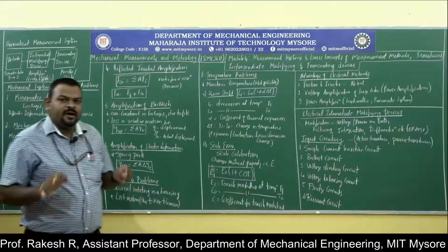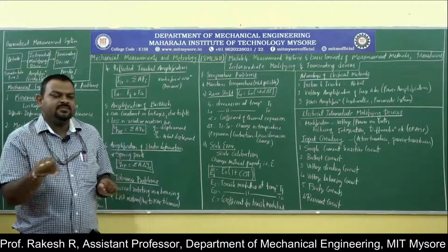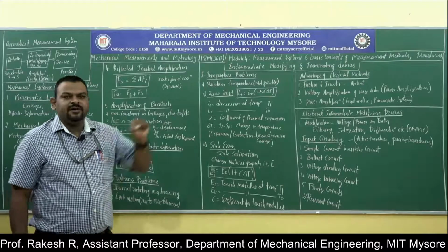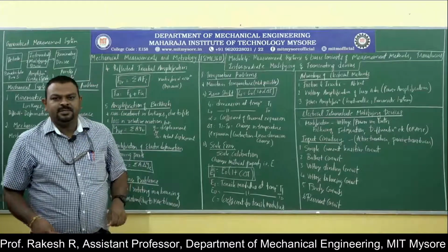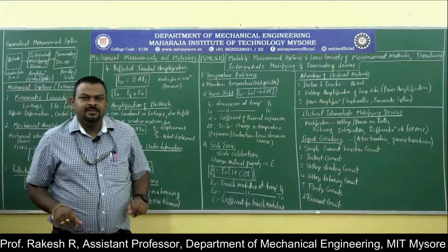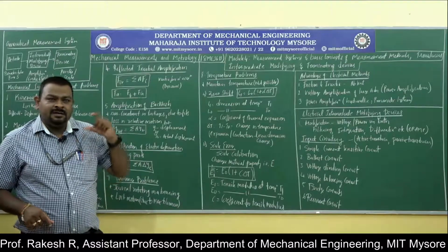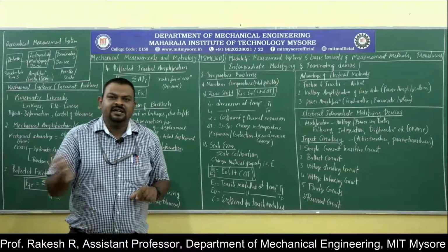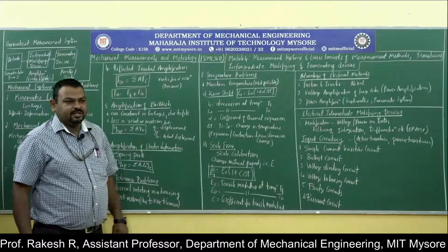The tolerance problem you have to take into consideration: proper design of fits must be employed, and proper design of tolerance must be given for the several types of fit based on the applications. That is very important. Sometimes I don't want a push fit, I want only a clearance fit. In such cases, the component will be designed so that a transition fit is not required. Directly you can give a clearance fit itself. So these problems you have to take into consideration.